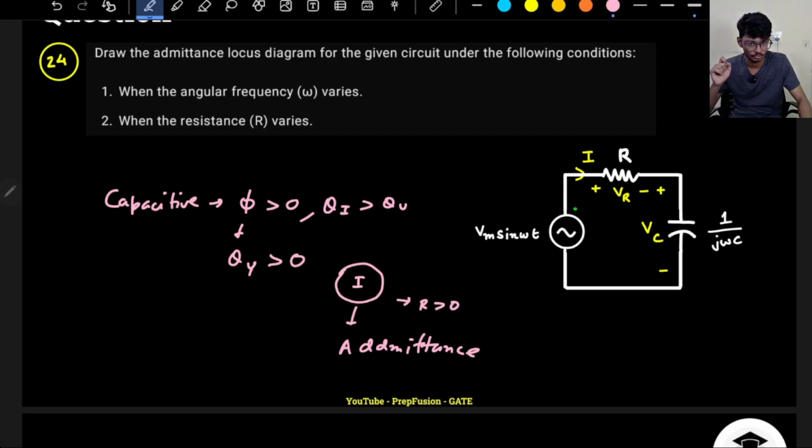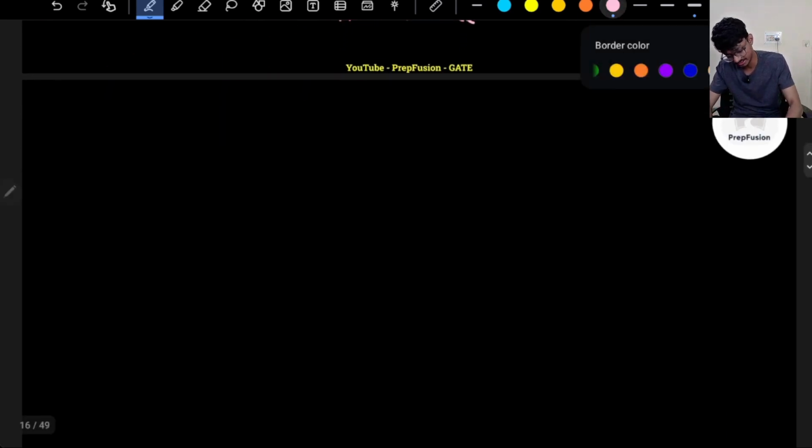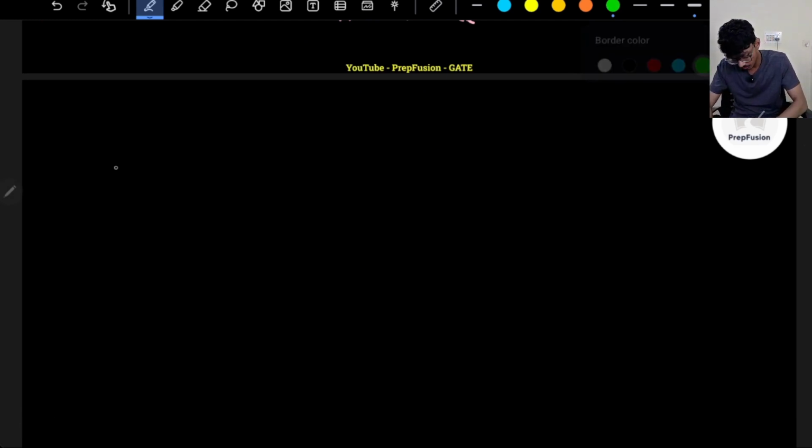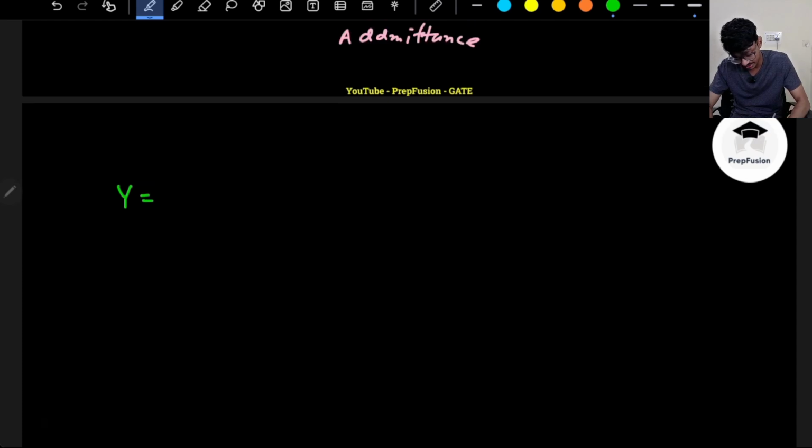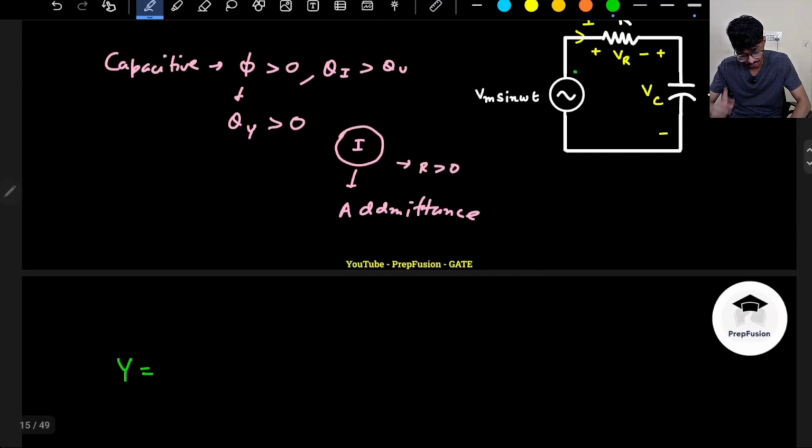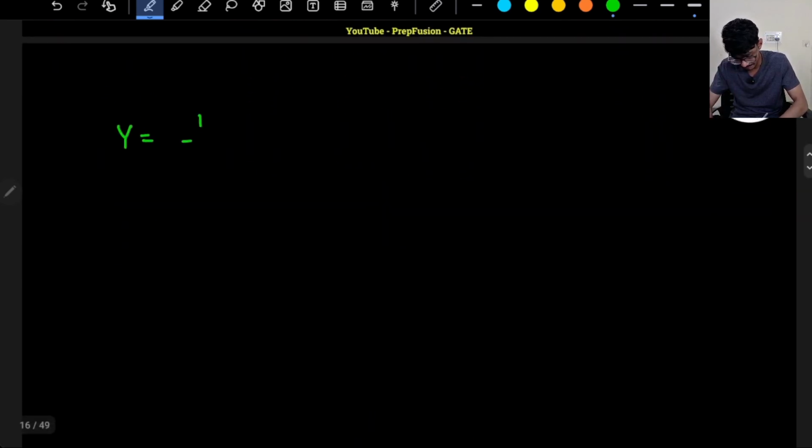That I will prove to you as well. Like we will see. Okay, so what is the admittance value basically? Intuitively, this is what you can see. In an interview as well, this is how you explain, without plotting anything. So what will be my admittance? Admittance will simply be 1 by Z, correct? And Z is basically R plus 1 by j omega C.